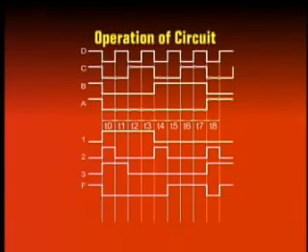Similarly, at intervals T1 to T4, the active low inputs A, B, C, D are 0, 0, 0, 1, 0, 0, 1, 0, 0, 0, 1, 1, and 0, 1, 0, 0, which actually represents the numbers 1, 1, 1, 0, 1, 1, 0, 1, 1, 1, 0, 0, and 1, 0, 1, 1. The output is 0, indicating that adjacent ones have been detected.